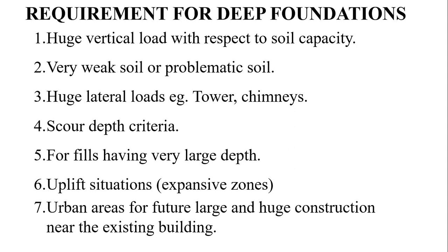Huge lateral loads act on certain structures such as towers or chimneys. On towers or chimneys, we expect lateral loads, which is nothing but a high amount of air or wind pressure acting on them. To resist that wind or air pressure, we need to adopt a deep foundation. We also adopt a deep foundation to reduce the scour depth.